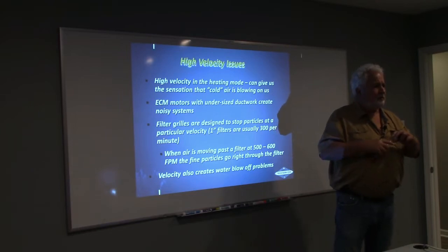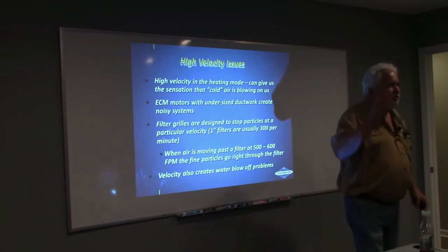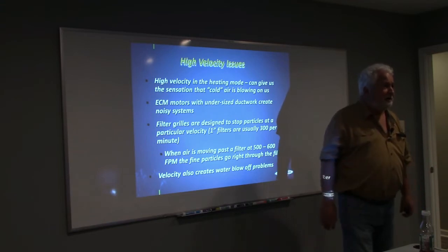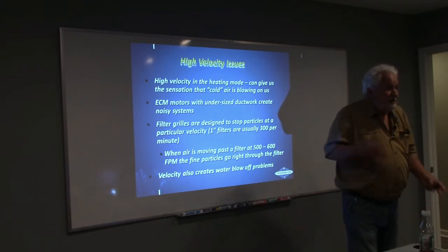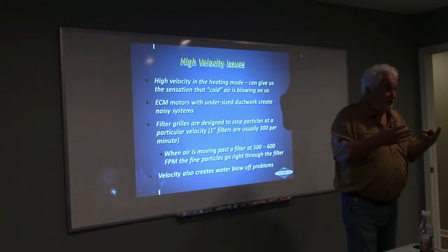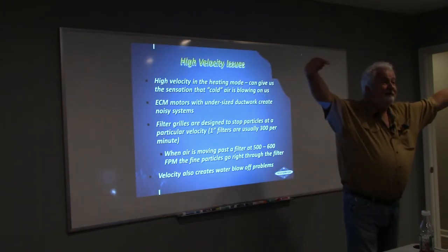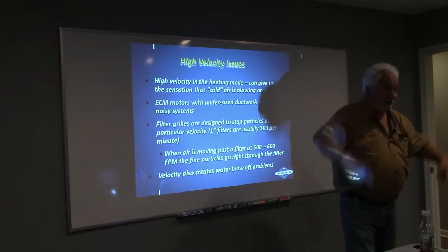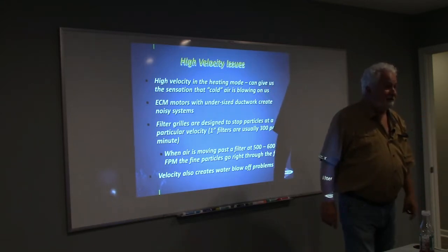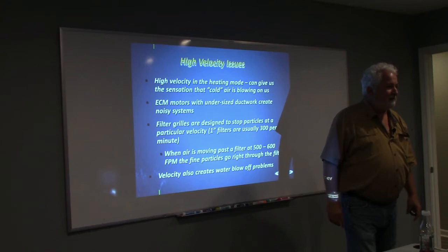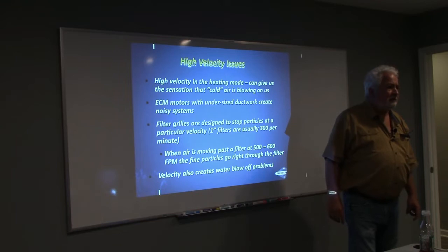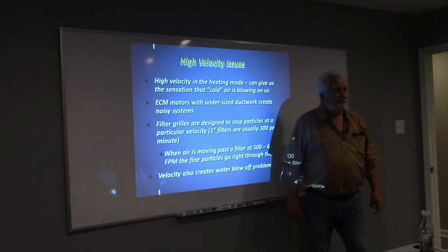That could be a sign of... How cold is that coil now, because you've got no heat? Very cold. Okay, if that coil is really cold because you're not putting any heat on it, that's where all the fungi starts growing, is that right? Yeah, so it starts growing inside. That's actually a sign of high moisture, low airflow, or incorrect ductwork size. But if you figured out that you've got no leaks or anything like that, that would be the next option.